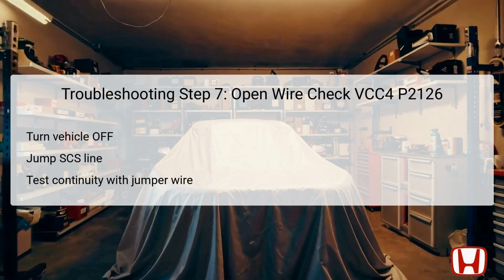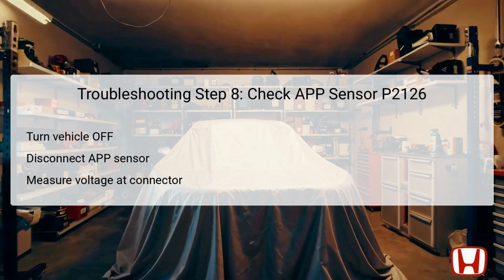If continuity is confirmed, this suggests that the VCC4 wire is functioning correctly and prompts a final examination of external sources related to the DTC. However, if results show no continuity, further inspection and repair of the open circuit between the PCM and APP sensor line are necessary. For the next troubleshooting step regarding DTC P2126, you will focus on the APP sensor itself.